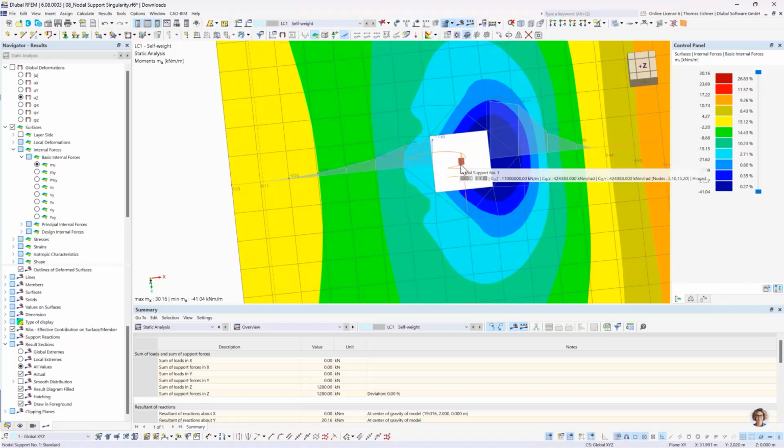So the problem is the pointy force must develop over the space. Right now, if we apply it to this rectangle, we would have a pretty big area it could go to. But the smaller these finite elements get, the smaller the area the force can distribute around.